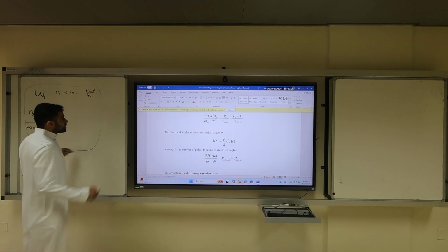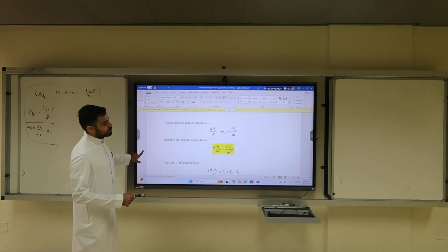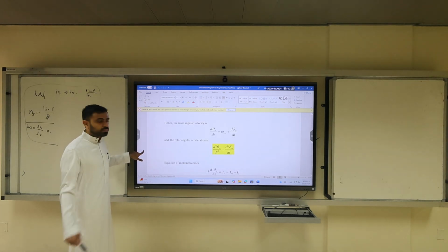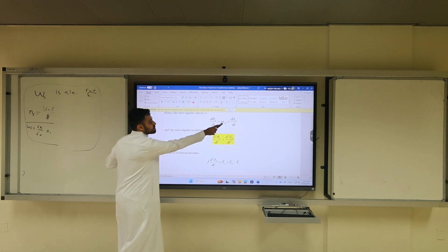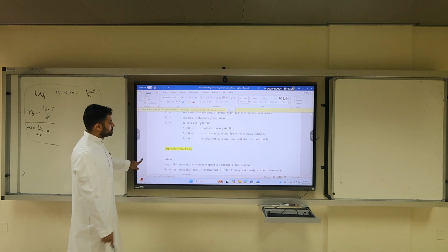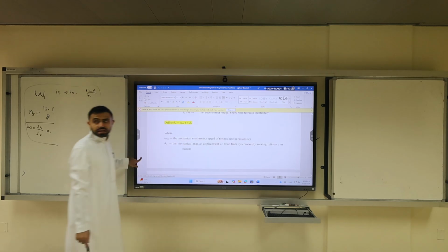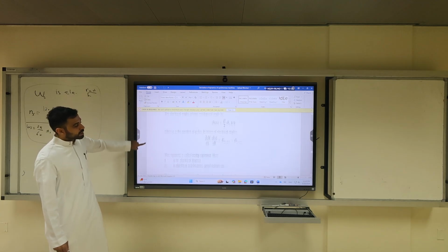The one we had earlier with the torque was the mechanical. To get the mechanical, you have to measure how many mechanical rotations. Clear? So this omega_sm is mechanical. Go back to the definition. Omega_m is the mechanical synchronous speed, not electrical. So we convert everything to electrical.